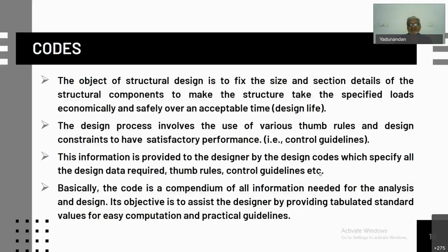The object of structural design is to fix the size and section details of the structural components, to make the structure take the specified loads economically and safely over an acceptable time. We fix up that the structure lasts a certain lifetime. Depending upon the type of the structure, we fix up anywhere from 50 to 100 years. And then we have to see that it performs well and steadily over this design life.